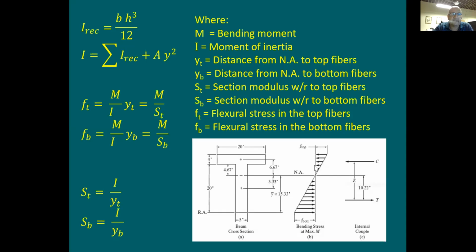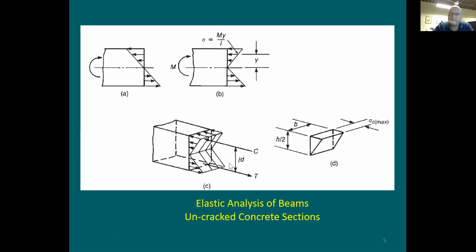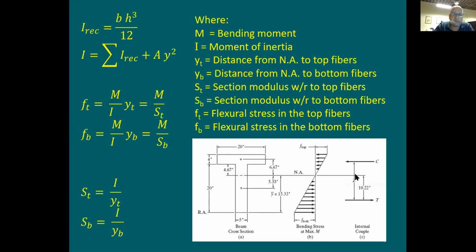If you like to do integration for all the forces here, for this volume of this stress distribution on this T shape, it gives you a force equal to C. Same thing, if you do integration of this stress distribution on this web, it is going to be equal to the tension force T. At the end, T needs to be equal to C. And the distance between the two, you can call it Z, or you can call it jd here, doesn't matter. I'm just going to go here with Z.